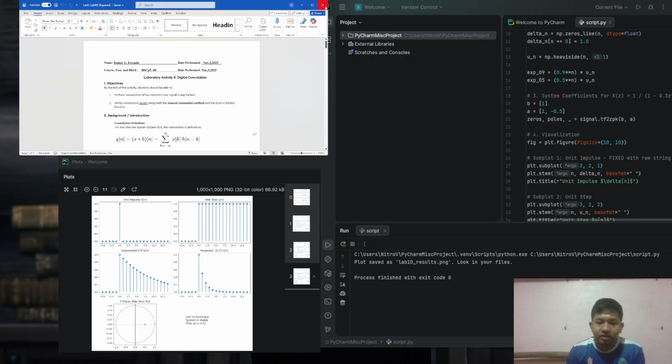In this activity, we are tasked to also explore the inverse transform, so we need to solve that using Python. And also analyze the stability, which is the location of the poles in the Z-plane. So in this test piece, we had a pole at 0.5.